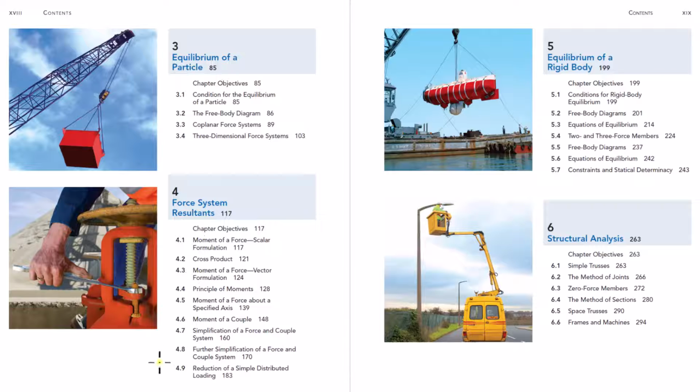We also learned how to work with distributed loads. So the majority of the time we're considering the concentrated force simplifying assumption. So we just put the force on something with an arrow like that. And when we do that, we're assuming that the area over which the force is applied is small, because unless you're dealing with a body force like gravity or electricity or magnetism, it's going to be a contact force. There's always going to be some area of contact. If that area of contact is small relative to the entire body, you can just put a point force like this. But if the area is not negligibly small, you have to use a distributed load.